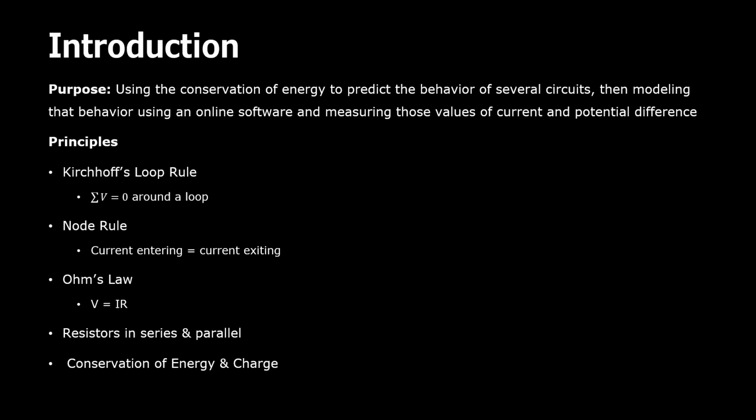And so, the principles we're using: Kirchhoff's loop rule, where the sum of all the voltages is equal to 0 around a full loop; the node rule, which is that the current entering is equal to the current exiting; Ohm's law, V equals IR, which is voltage equals current times resistance; and then resistors in series and parallel, and the conservation of energy and charge.